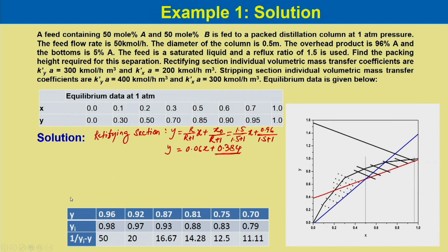Similarly, for the stripping section, we can write y = L'/(L'-W) x - W/(L'-W) xW.